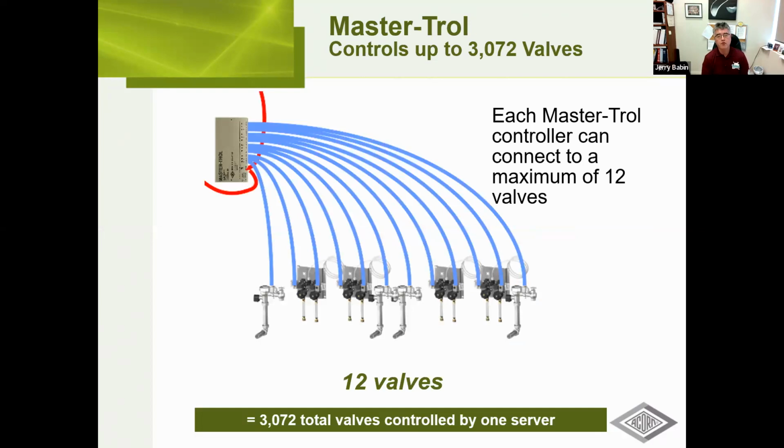And then as you see from the controller, you've got lines running to each solenoid valve. Now what Acorn provides, basically this gives you a good view of it. So we provide the fixture, the solenoid valves, and control boxes at the fixture, the lines from the fixture to the controller. Everything from the controller going back to the computer would be provided by the plumber. Their controls tech would provide all that. But everything from the controller going back to the fixture, that is all part of what Acorn Engineering provides.